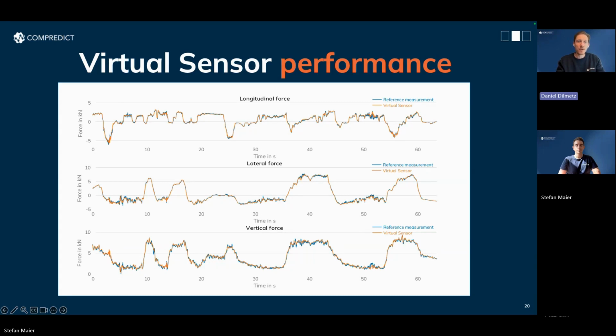With these metrics, we are trying to incorporate a so-called multi-objective optimization in order to capture, as I said, the entire spectrum. So we calculate the average deviation in comparison to the reference signal, which is done by the root mean square error, for example.